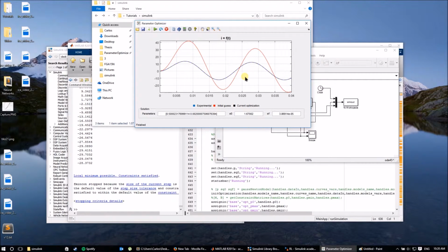And last but not least, I can give you some tips regarding models that depend on the time. They are always a bit tricky. There are two things I could give you as advice, because I have been working with PMSM, and I have found some problems that you may encounter if you need to use the time in your models. First one is you need to synchronize things.